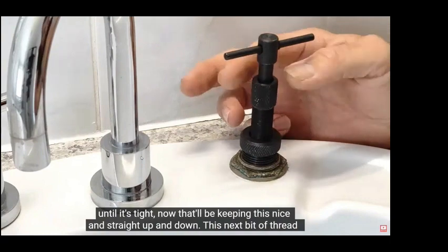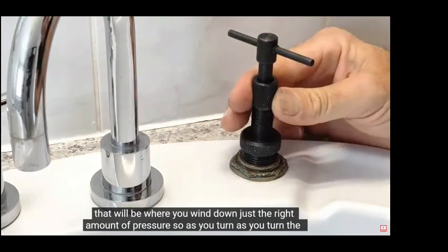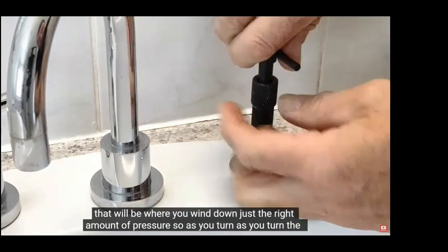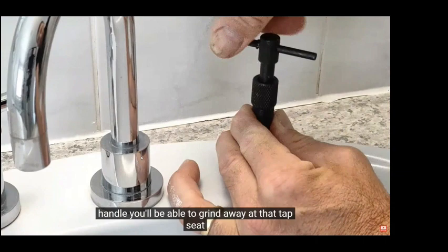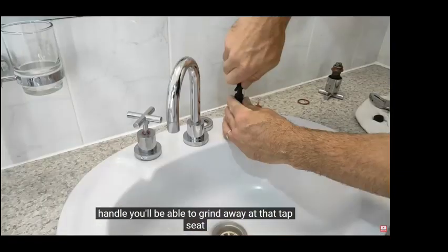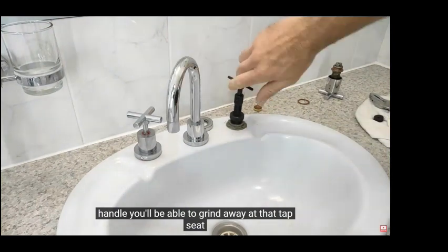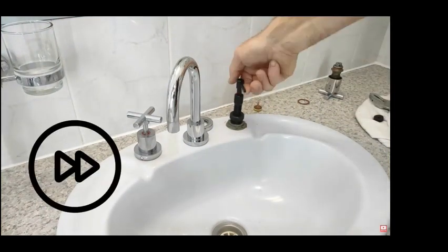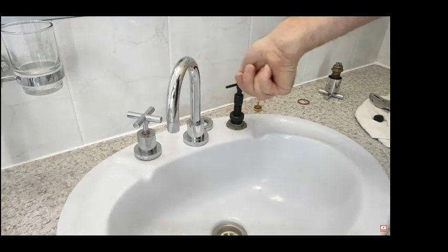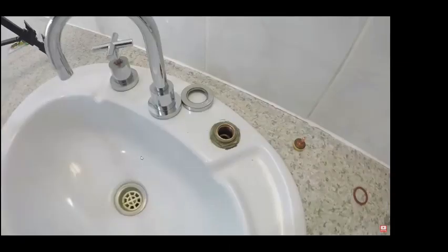So there he's tightened it up so it's just held centrally in position. They're fairly sloppy, especially the tapered ones. And then you hold that against it, otherwise it'll just keep tightening as you turn the top bit. Now he's over-tightened it because it's probably not locked up. It hasn't bound up, so it might be okay. But you're usually just holding the other two bits off each other. Spin around a few times.